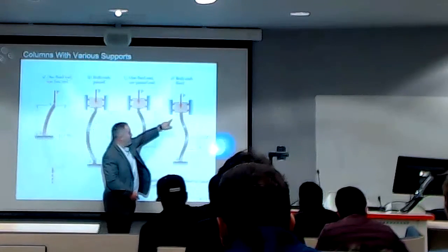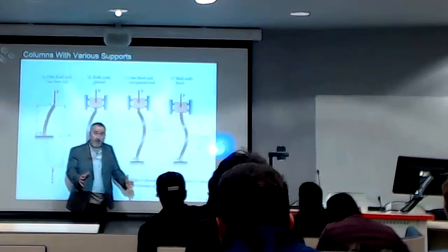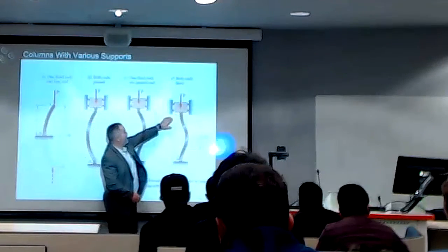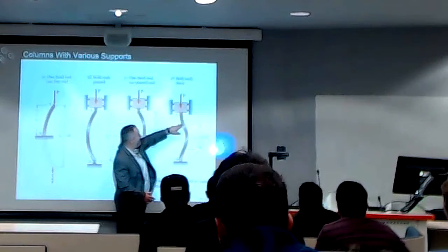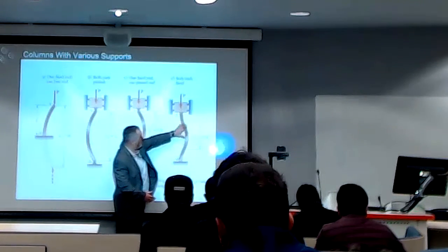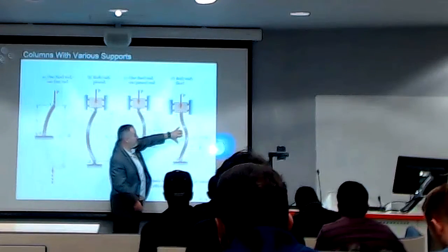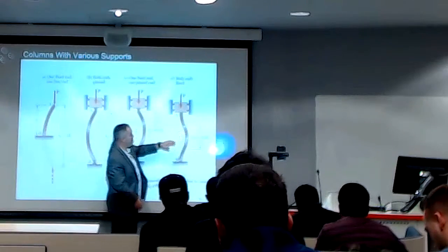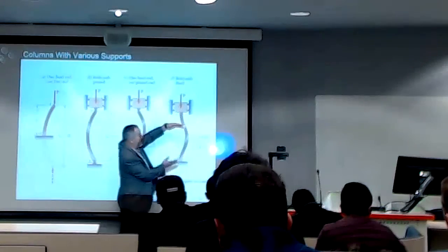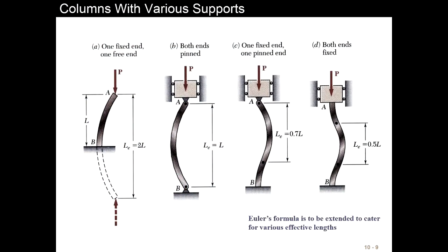And this is like the more common scenario. You know, in terms of a concrete column, it's fixed in the bottom, it can't rotate, and it can't rotate at the top. So you find that this is a stiffened area, so it'll be really this half of the column that it can fail in buckling. So when you have it fixed at either side, it's the equivalent of having half of if it was pinned either side. You have to remember the four scenarios.